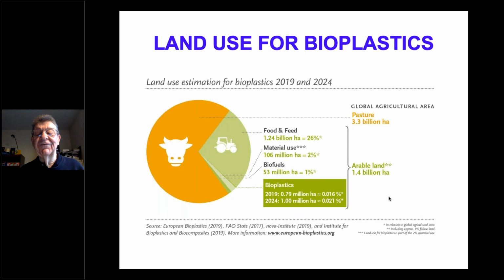And also there's been a big development of the stereochemistry of the product. Since lactic acid is stereoisomeric, you can make different forms of the polymer. The original polymers were a copolymer of D and L with mostly L, a little bit of D. Now we can make homopolymers, which are all D or all L, which give us much higher heat distortion temperatures.